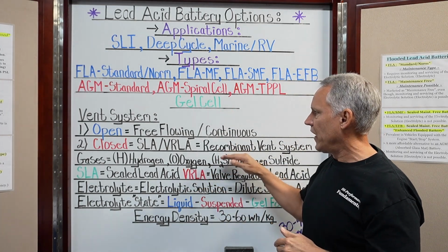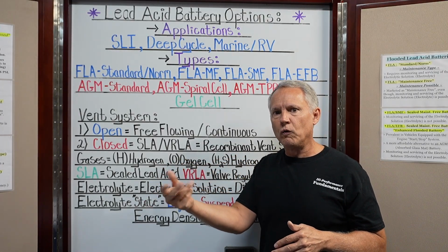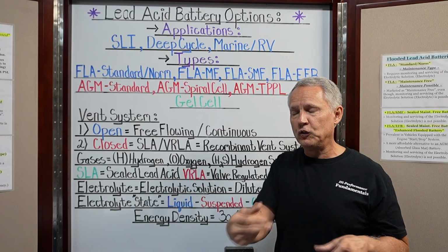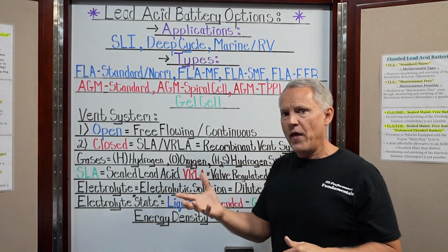Either the battery is failing internally, right? You have a cell issue, or maybe the alternator in the vehicle or the generator is overcharging the battery, which is going to overheat the battery, which will produce hydrogen sulfide. You should not smell that, right?